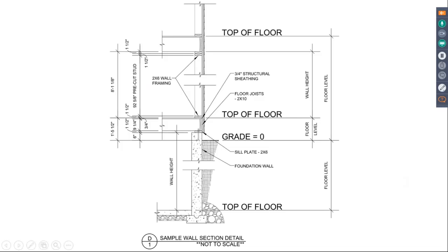So as we can see, again, coming back to this diagram, the wall height for our foundation wall, which is here, here's the wall height of our foundation wall. And as drawn in this detail, it's going from the top of this slab here to the top of the foundation wall as it projects above grade. And so it's up 6 inches above grade as we looked at before.